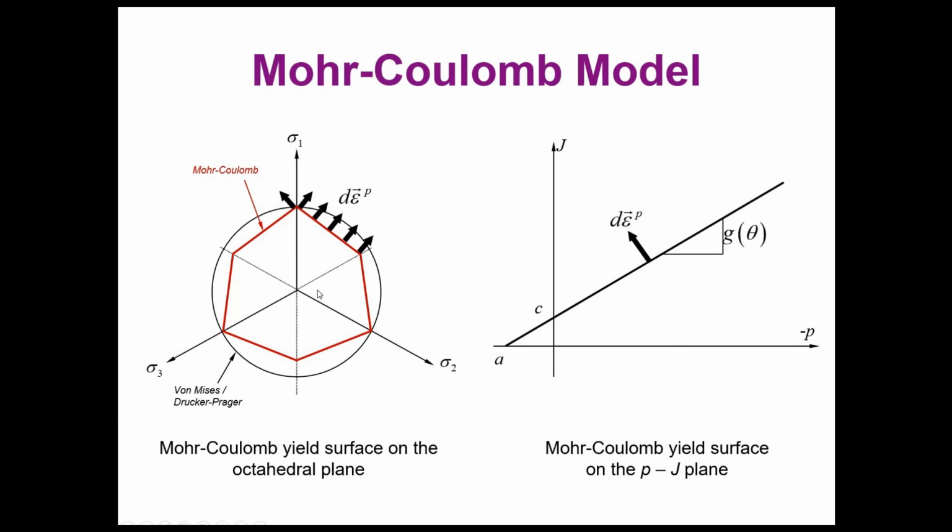So you can recover the concept of the Mohr-Coulomb failure criterion in 2 dimensions if you project this model in 3D on this space where you have the invariants of the deviatoric stress tensor and the average axial stresses in the horizontal axis.